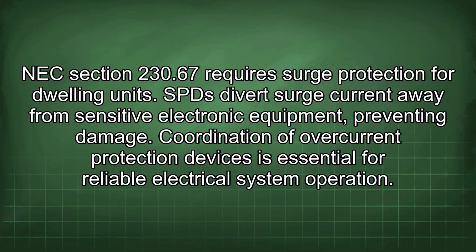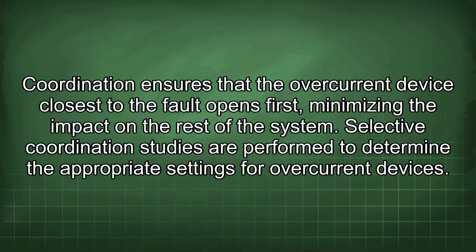Coordination of overcurrent protection devices is essential for reliable electrical system operation. Coordination ensures that the overcurrent device closest to the fault opens first, minimizing the impact on the rest of the system. Selective coordination studies are performed to determine the appropriate settings for overcurrent devices.